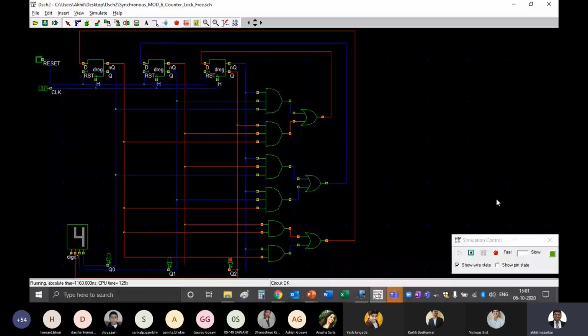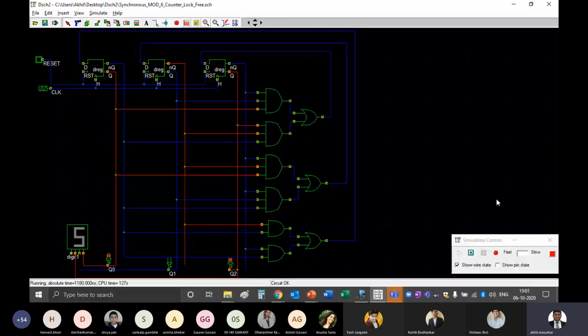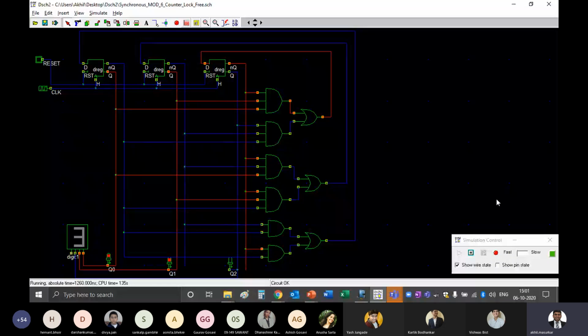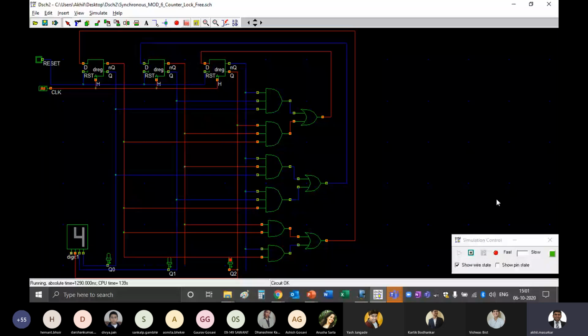Now you can have 3 approaches to the same problem. Let's say the problem is a traffic light signal control at a crisscross junction where there are 4 roads. You can solve it using a microprocessor circuit, but it will be slightly difficult because the number of input and output pins that a microprocessor has is restricted. You can increase the number of pins by using an IO controller, but then you need to design the PCB for that, which is slightly difficult design-wise.